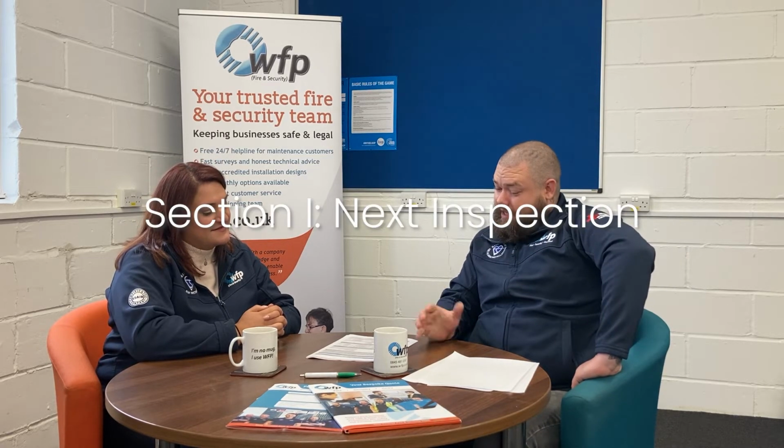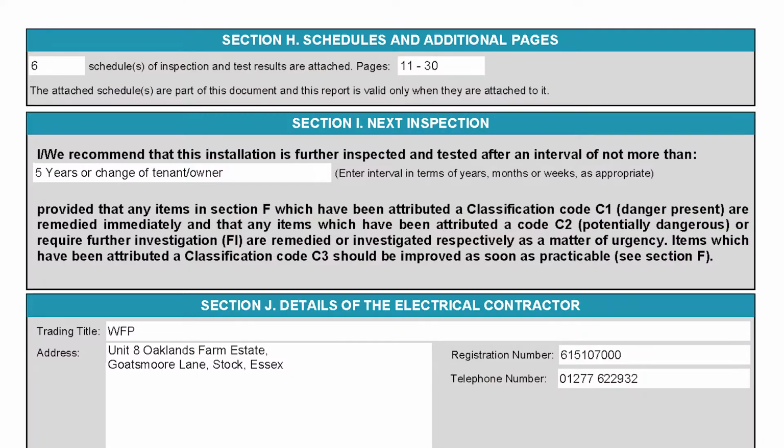Section I, again, that's important because that's telling you when your next inspection is due. And that will also be a sticker on the panel as well. It would say the date of your inspection and the date of your next inspection. Absolutely, but the real big thing here we see all the time is if there's a load of remedial works, a company will say it's due in 6 months. That is not what this section is saying.